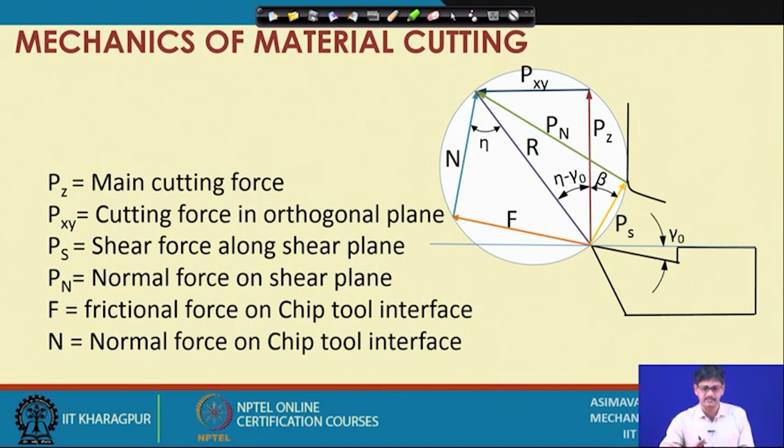There is a single resultant force. What we know about that force is that it is on the orthogonal plane. So, if this is pi O, the orthogonal plane, we have the resultant force, that is the resultant of all interactions, if this is R, pointing upwards if we consider the force on the chip. The tool is applying this force on the chip.